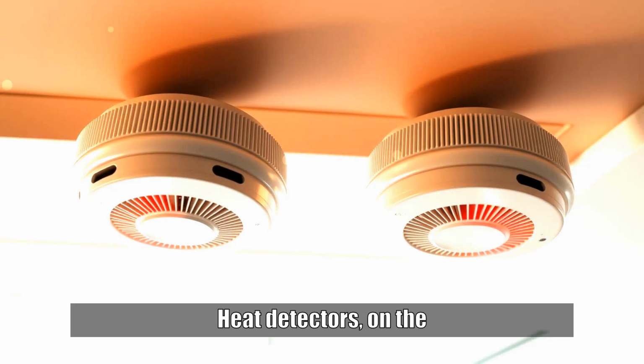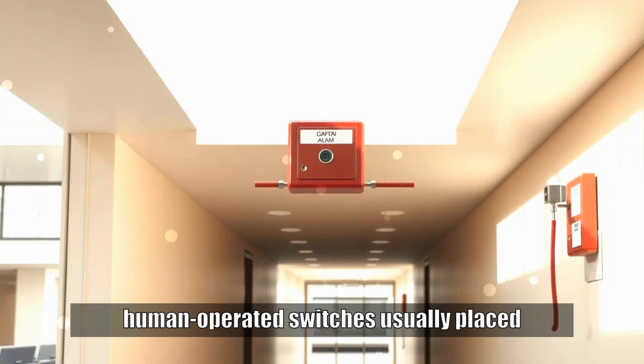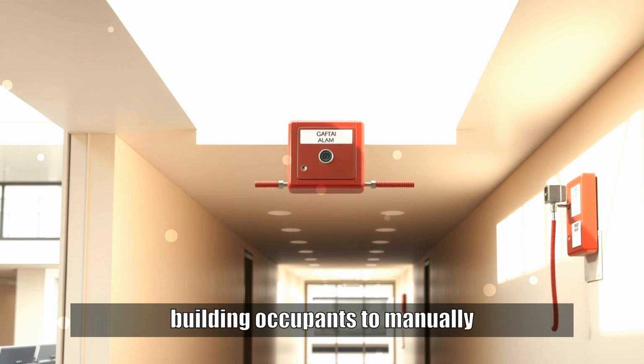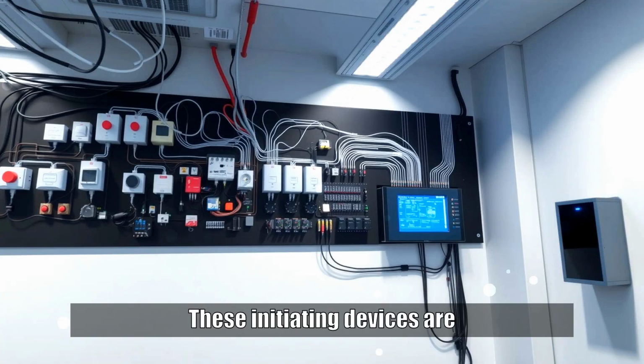Heat detectors, on the other hand, react to an increase in temperature or the rate at which the temperature rises. Manual pull stations are human-operated switches usually placed along evacuation routes, allowing building occupants to manually trigger the alarm. These initiating devices are interconnected by wiring or wireless technology and are constantly monitored by the brain of the system, the Fire Alarm Control Panel, FACP.